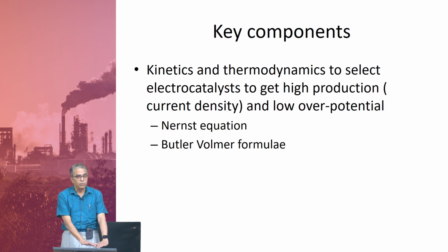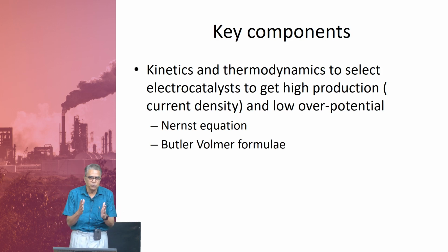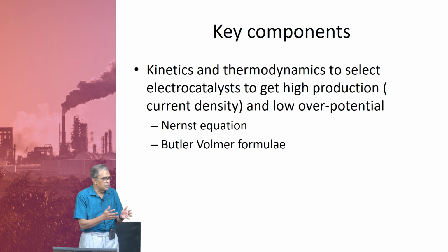So, from there you can get to know the potential between, say, the electrodes for producing caustic soda. In order for that reaction to take place, we have to apply electricity, and that application of electricity requires some voltage. Is there some idea of what is the absolute minimum voltage that I have to have, below which the reaction will not proceed? Thermodynamics gives you that. Take a reaction, for instance: what is the absolute best equilibrium conversion that you will have at a certain temperature and conditions? You do not have to do an experiment, but you can get a good guess of what it is.